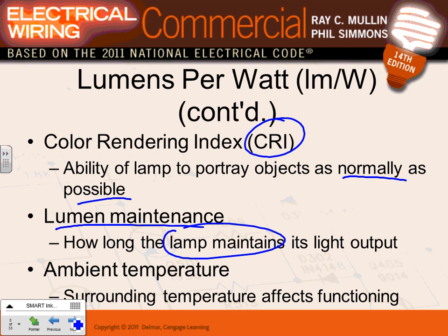So there is a certain operating temperature that the fixtures want. Some of them are rated -20 Fahrenheit to say 110. I'm just throwing these numbers out here, or in Celsius, -10 Celsius to 40 Celsius. These are the operating temperatures. The closer you get to being cold or hot, the less lumen you get out of the fixture, and the more likely the fixture will prematurely die on you.